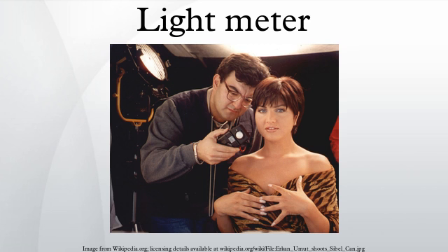Use in illumination. Light meters or light detectors are also used in illumination. Their purpose is to measure the illumination level in the interior and to switch off or reduce the output level of luminaires. This can greatly reduce the energy burden of the building by significantly increasing the efficiency of its lighting system. It is therefore recommended to use light meters in lighting systems, especially in rooms where one cannot expect users to pay attention to manually switching off the lights. Examples include hallways, stairs, and big halls.